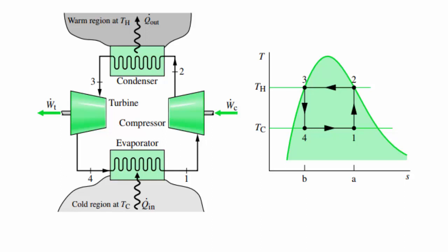During this process the pressure is also decreased, so this saturated vapor goes into the compressor, where its pressure is increased to a certain point, which was the pressure at the start of the process. Now that high-pressure refrigerant goes into the condenser, where its temperature will be dropped to a certain point which you have set in the refrigerator.